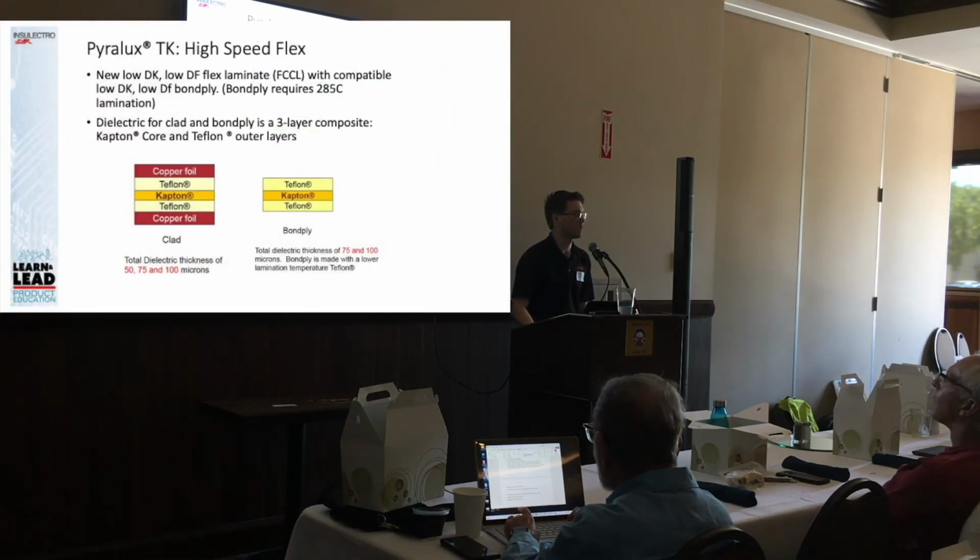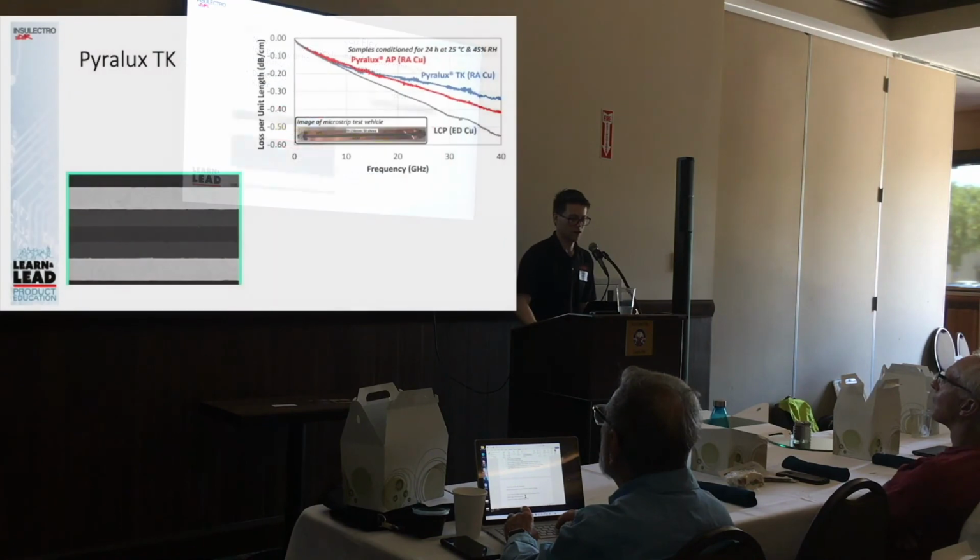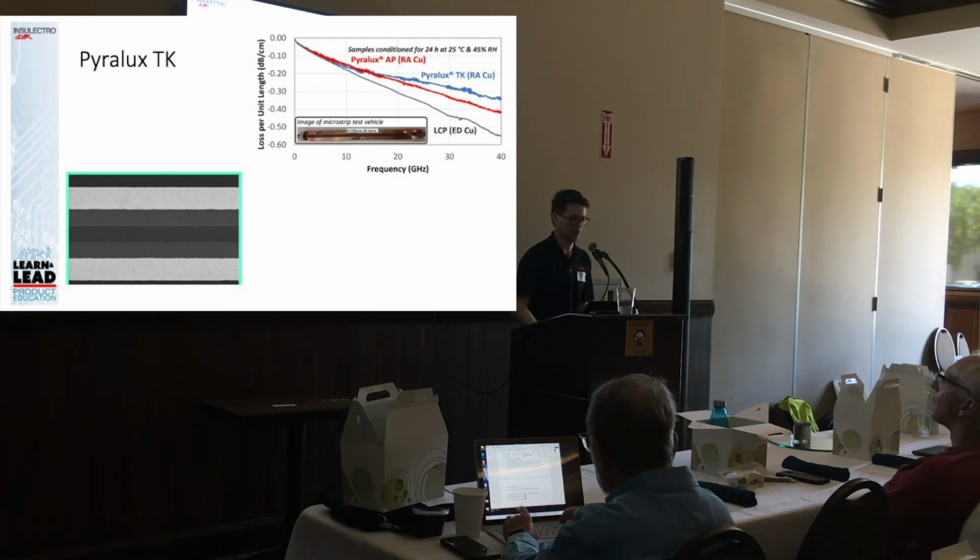We also have a product called Pyralux TK. It's a Teflon or FEP coated polyimide material, and if you've ever worked with fluoropolymers, you understand that the orbital structures of those composites don't like electrons, which is great for designers because we can use that to get good electrical characteristics. What you can see here is a cross section SEM scan. You can see the differences in where we put that FEP with the polyimide. And then in the top right-hand side here, you can see a TK flexible clad laminate and its insertion loss values.